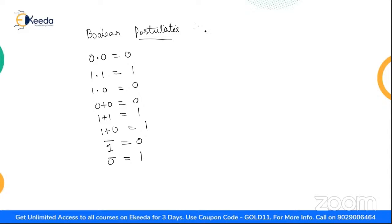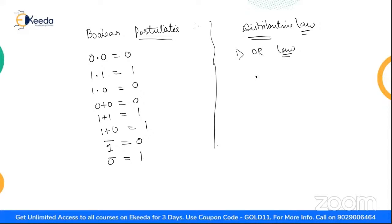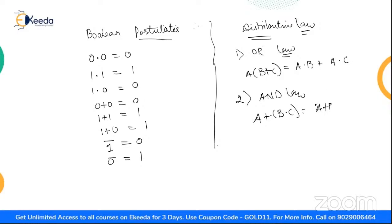Another law is the distributive law. These are Boolean postulates. The first law is called OR distributive law: A into B or C is equal to A into B plus A into C. The second law is the AND distributive law: A plus B dot C is equal to A plus B dot A plus C. Okay, remember this.